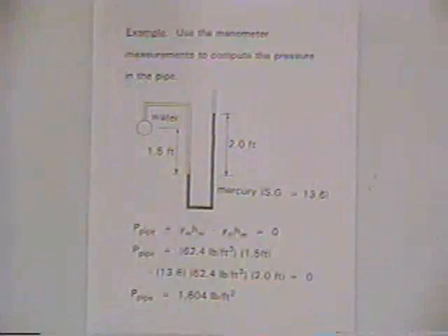Another problem applying the same concept is a manometer. A manometer is a measuring device. It's one of various mechanisms for measuring the pressure in a container or a pipe. And we have to apply the principles of fluid statics to be able to convert a manometer reading to an actual pressure measurement in the container.